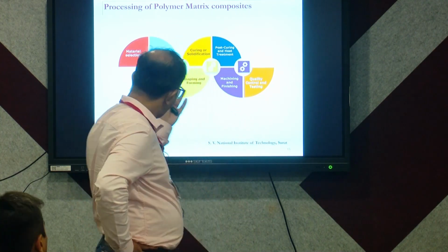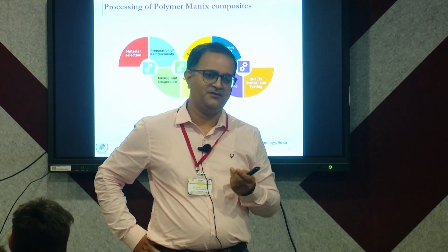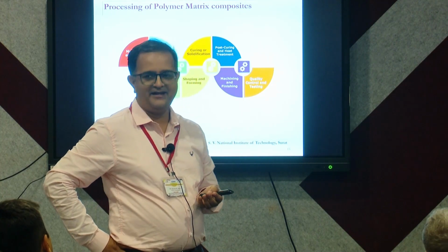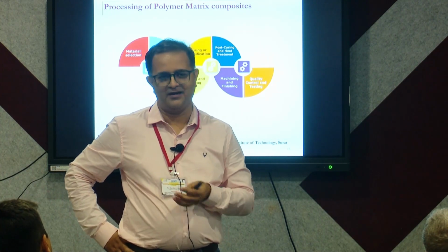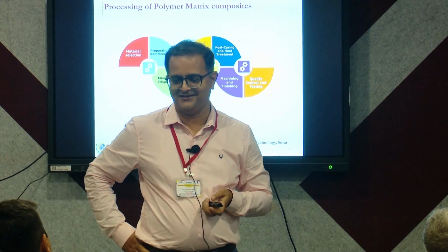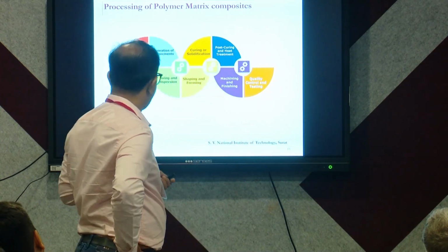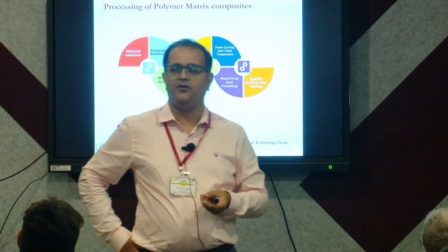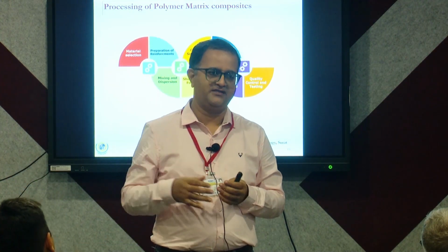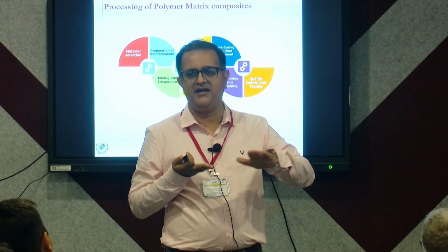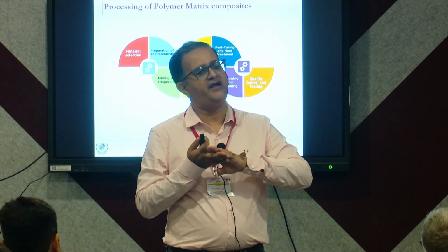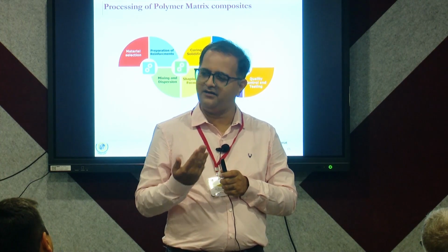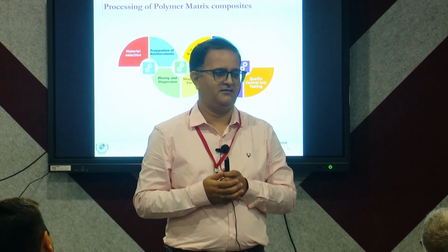So post curing becomes, instead of UV curing, he thought let me use the daylight, and daylight brought night into his experimental work. So post curing and heat treatment also get involved in most of the processes, and then you need to finish the part. Often, tomorrow also you will see in one of the setups, one of the sides is perfectly finished and on the other side you feel that all the roughness has come on one side only.